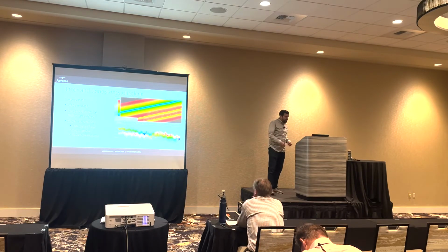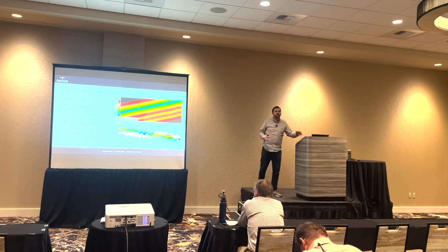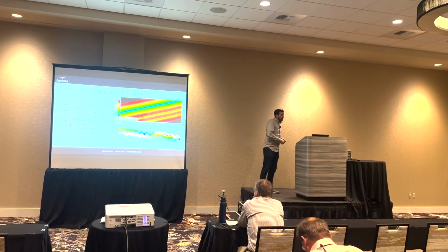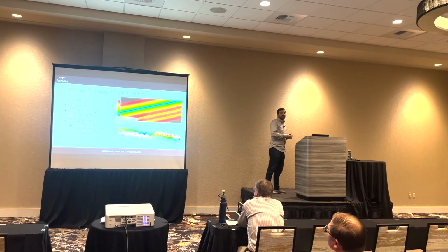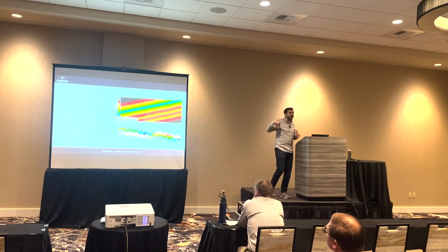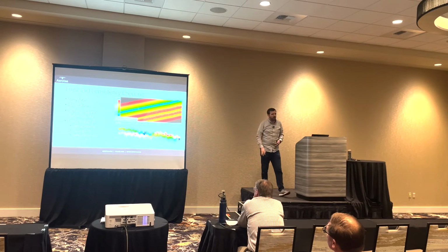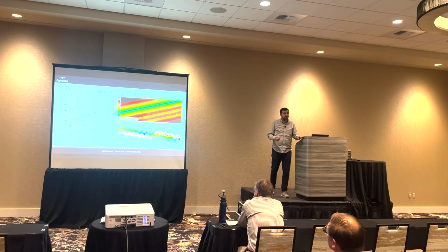A great example of that, this is one of those things that came up, is actually doing error and consistency checking. This should be done very early on in the process, checking for consistency in LiDAR. LiDAR does create noisy data. There are artifacts, windows can reflect light in funky ways and create points that are above the drone. There is noise. There can be gaps in data. The vegetation penetration is extraordinarily impressive, but it's not perfect. You might need to interpolate some gaps.